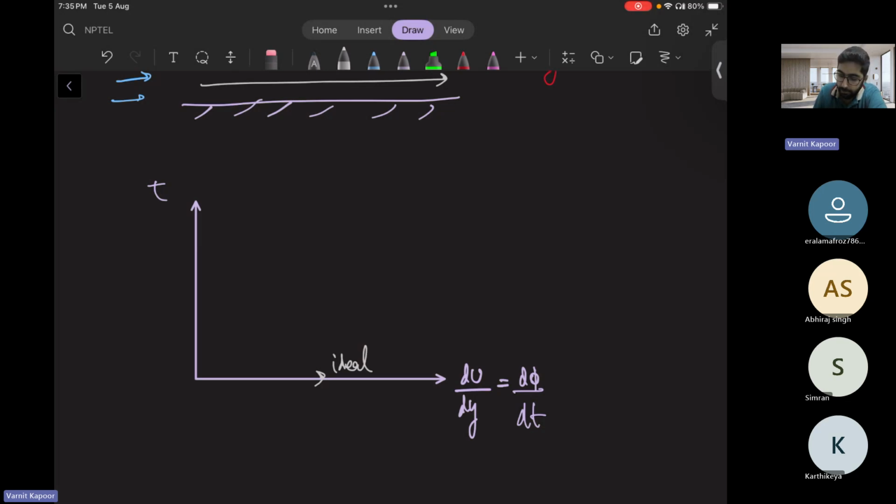Whereas solids behave where the rate of deformation is not there. Solids have a deformation, I told you in the first class, but it is a constant deformation. It doesn't have a rate of deformation. Fluids are those which have a constant rate of deformation. These are elastic solids. In the first lecture itself, the starting point was the difference between solids and fluids, if you remember.